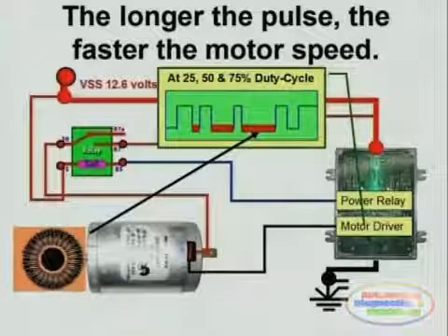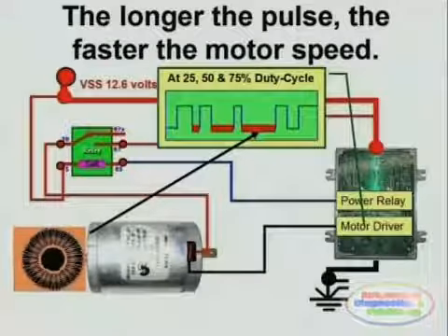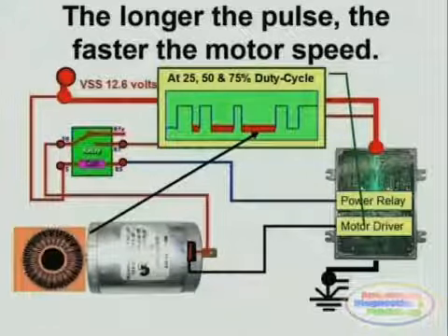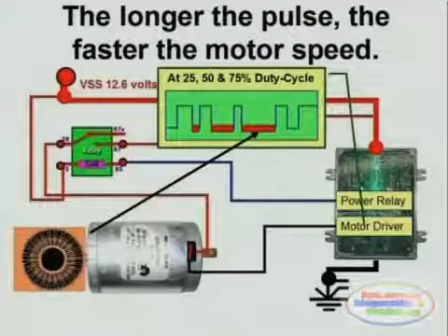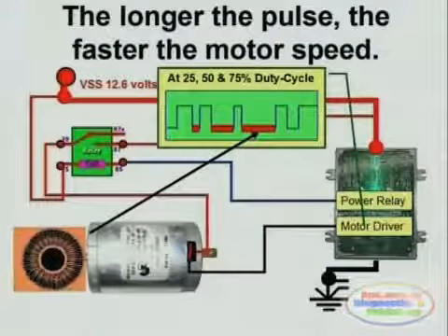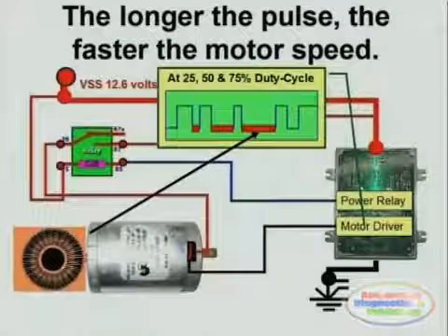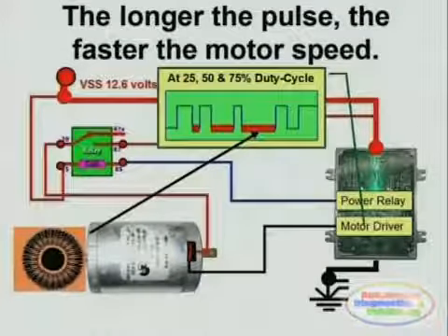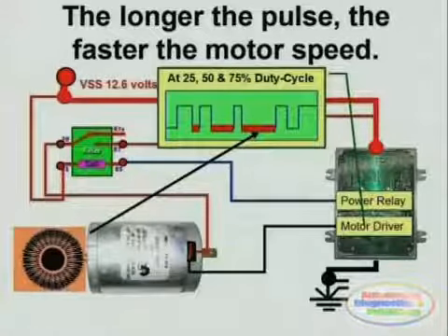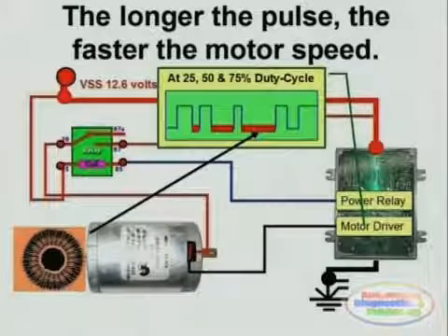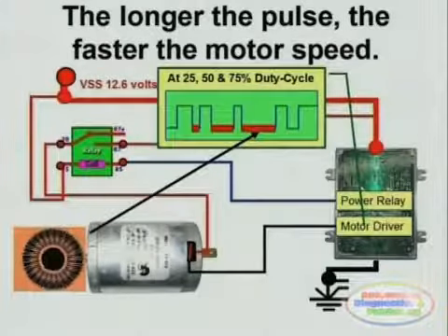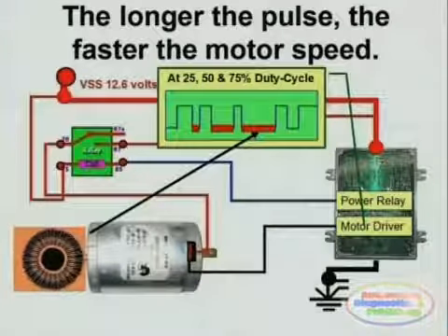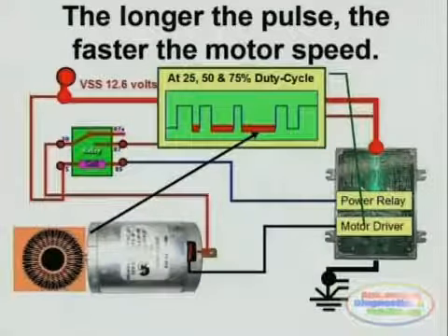You will need this type of arrangement in any system that is returnless. For example, the newer types of fuel systems that do not have a return line rely heavily on fuel control by controlling the speed of the fuel pump, and this again is done through a duty cycle controlled signal.